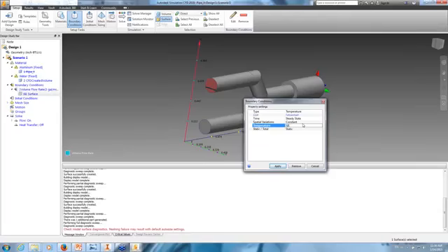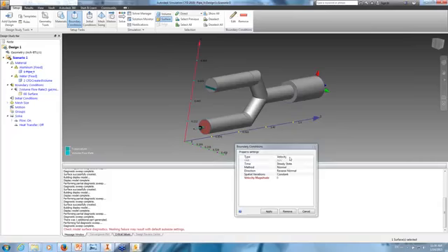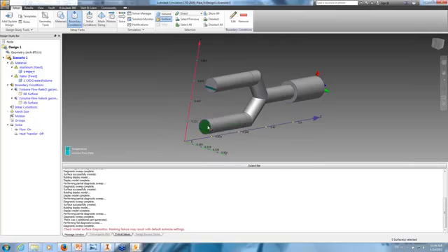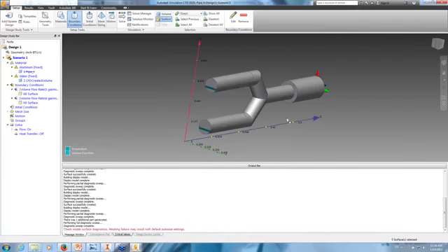degrees Fahrenheit. So we've got metric and English units. That doesn't matter. That's fine. This surface here is going to be similar but a little different. Also volume flow rate, but that's going to be, again, GPM, and it's going to be 4 GPMs, and it's going to be at 100 degrees Fahrenheit. So these two are my inlets.